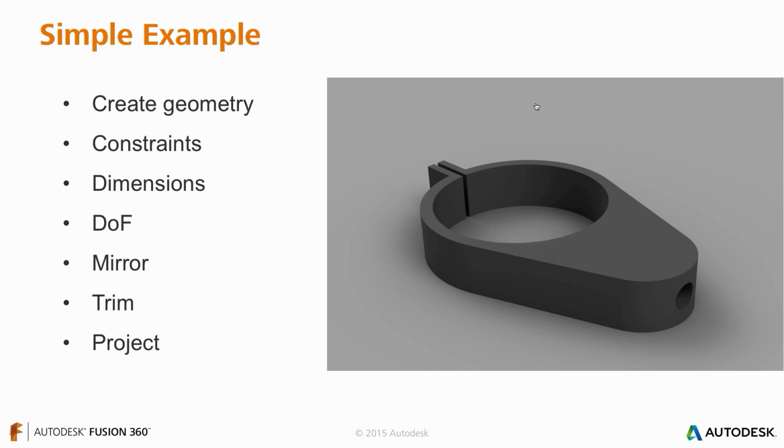So we can start things off just quickly making some definitions because I'm going to be referring to these terms throughout the webinar, so it's good to make sure that we're all on the same page. So what's inside of a sketch? In Fusion 360, there's mainly three things going on in a sketch. You have your geometry, and those are the shapes that you're drawing inside of your sketch. These are made up of sketch curves, sketch points, and when you connect these curves, they create profiles. So those are the three terms to keep in mind as we go through this.